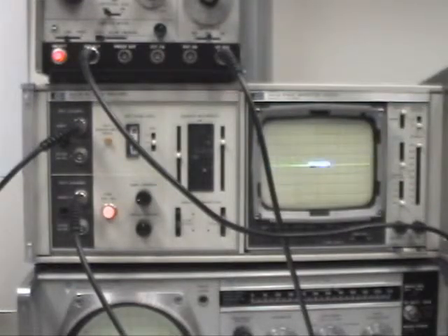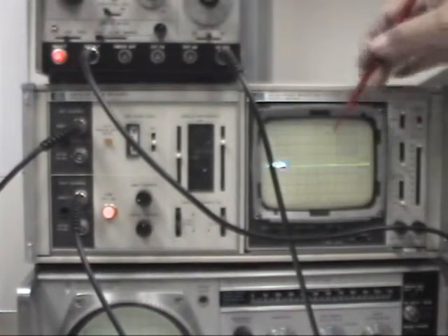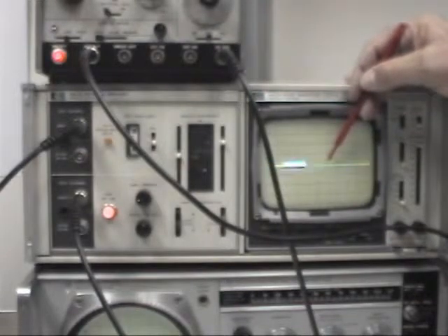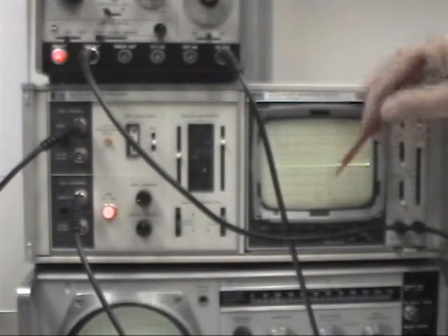To start with, we have the input run through the power splitter, so the reference channel and the test channel have the same amplitude, or fairly close, and we're going to set it up so that right in the middle of the screen is 0 dB. So we'll be able to read plus 40 dB and minus 40 dB from that point. We're at 10 dB per division, so we'll set it to 5 dB per division. You notice we went down off of the screen.